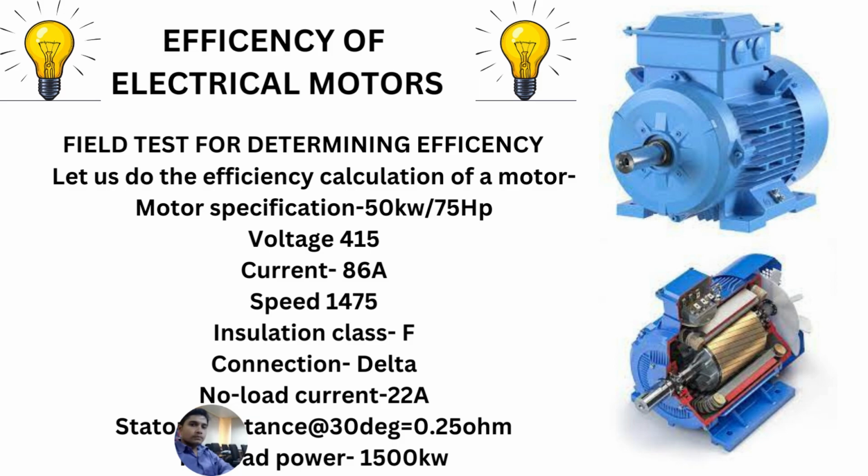Now, let us calculate the efficiency of a motor. For example, let us consider the motor specification as 50 kilowatt motor, voltage of 415, current of 86 ampere, speed 1475, insulation class F, connection delta, no load current is 22 ampere, and stator winding resistance at 30 degree is equal to 0.25.